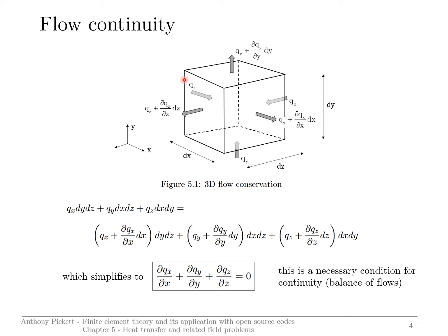So it can represent many different quantities, but in general terms, let's just say the inflow is Qx multiplied by dy dz, where this is the area, and so on. We have for the other terms Qy and Qz as shown here. That has to balance the outflows, which is given by these expressions summated here.